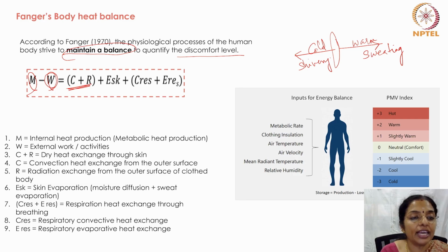This should be equal to the dry heat exchange through skin in the form of convection plus radiation, plus the skin evaporation, the moisture on the skin which causes evaporation and cools, plus respiration heat exchange because of breathing, which is a form of convection, and respiratory evaporative heat exchange.